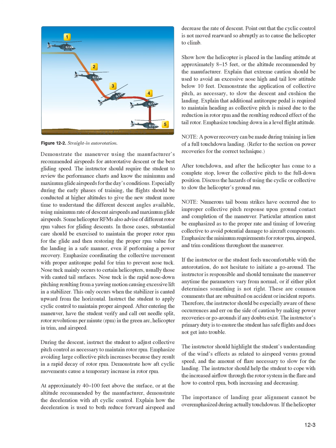Explain that additional anti-torque pedal is required to maintain heading as collective pitch is raised, due to the reduction in rotor RPM and the resulting reduced effect of the tail rotor. Emphasize touching down in a level flight attitude. Note, a power recovery can be made during training in lieu of a full touchdown landing. Refer to the section on power recoveries for the correct technique.